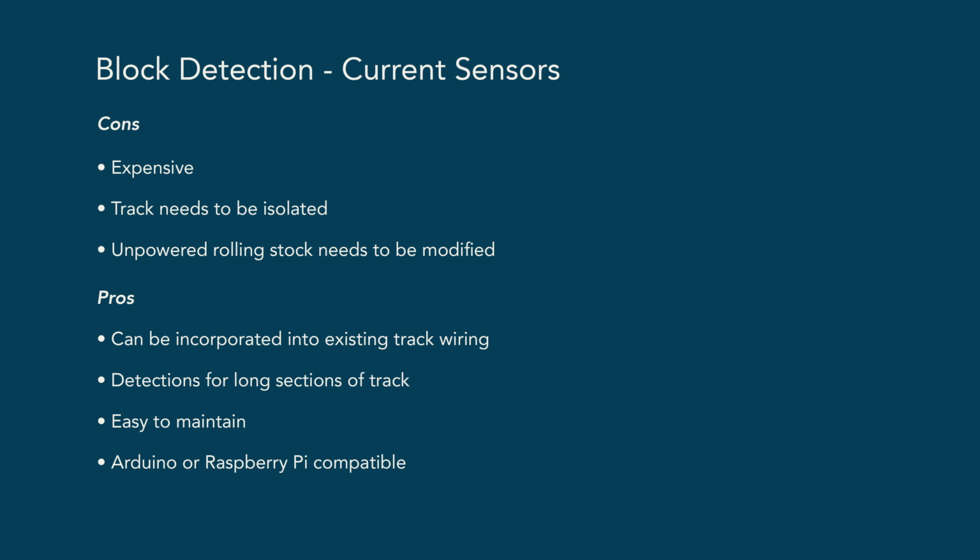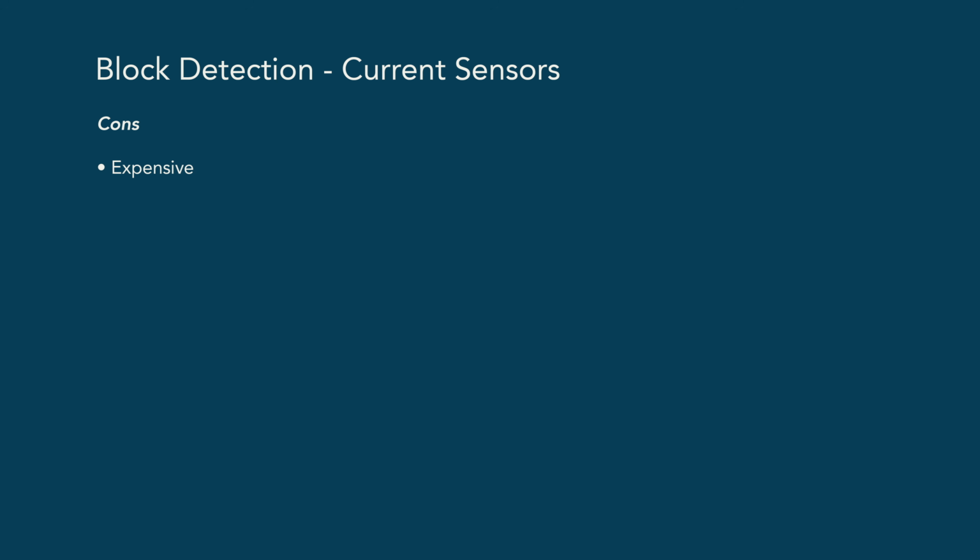My initial thoughts are that I'm going to concentrate on current sensing technology, as it requires me to think about electrically isolating areas of track that I want to split into blocks. I'm going to discount under the track optical sensors simply because of maintenance issues in replacing one should it fail. However, having optical sensors alongside the track could be a definite possibility later on in the build.